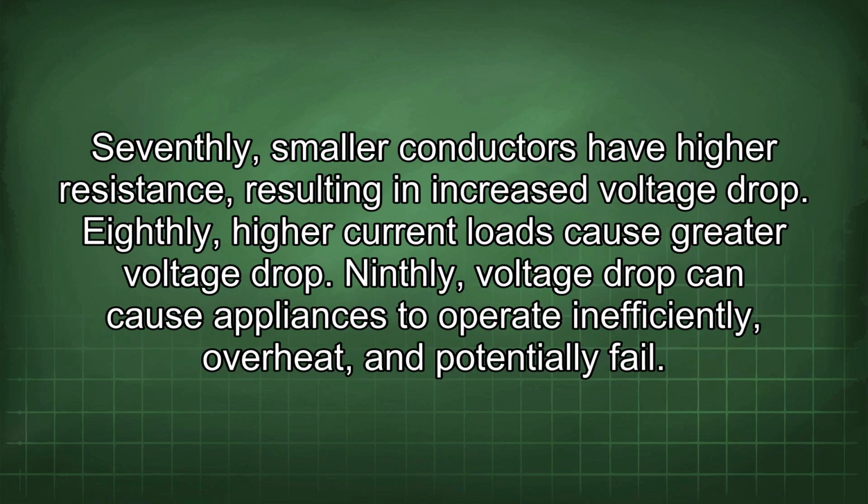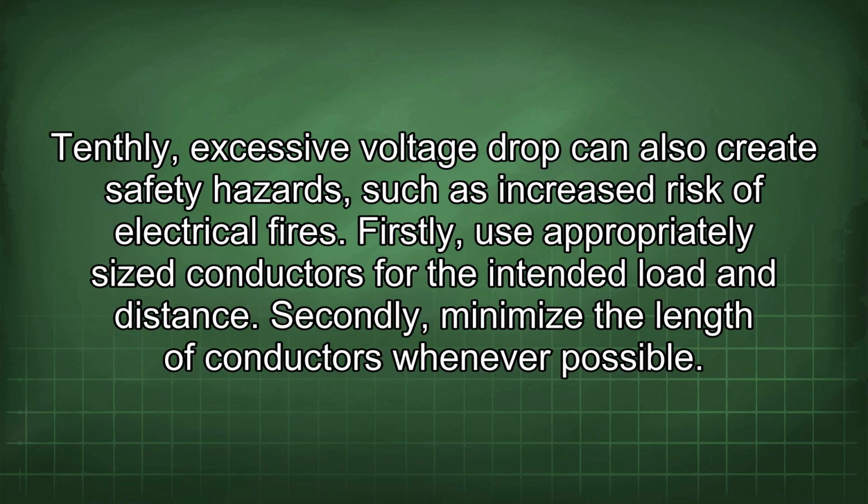Seventhly, smaller conductors have higher resistance, resulting in increased voltage drop. Eighthly, higher current loads cause greater voltage drop. Ninthly, voltage drop can cause appliances to operate inefficiently, overheat, and potentially fail. Tenthly, excessive voltage drop can also create safety hazards, such as increased risk of electrical fires.